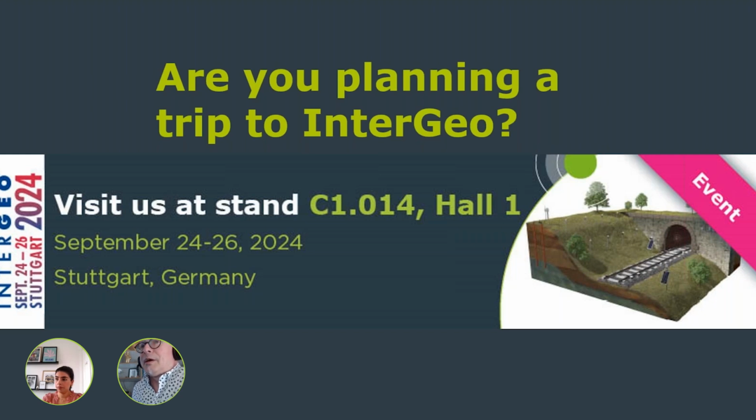A 2-second reporting rate, of course, requires a different power supply to the gateway. That needs some consideration of the data rate that can be transmitted via a SIM card. Maybe a better way would be to go via a USB or RS-232 gateway onto a local computer then. But it's possible from the point of view of the nodes to go to this high data rate.